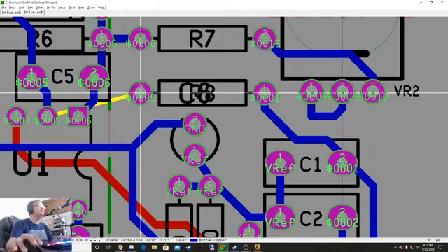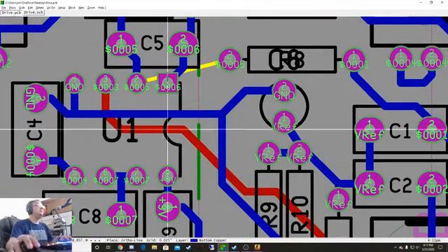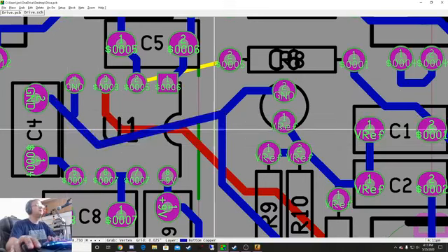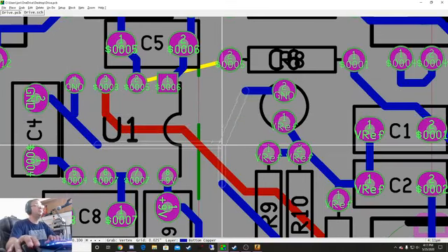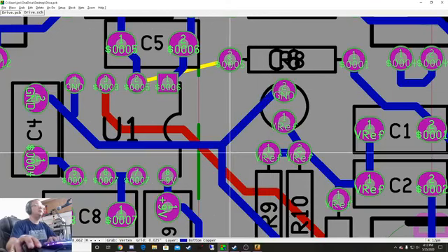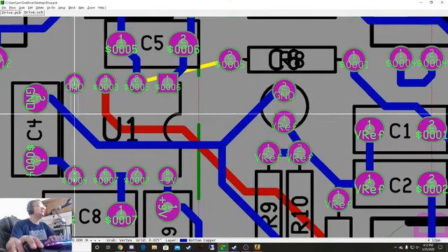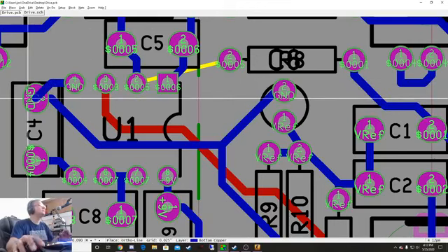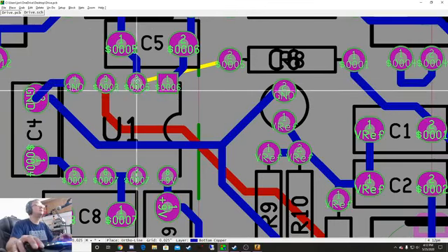This needs to go to net 5. So in order to get that to net 5, I need to go inside. So what I'm going to do is move this whole thing down. And I use the keyboard a lot. I'm using the arrow. So when you grab a line, you can use your arrow keys to move lines around.